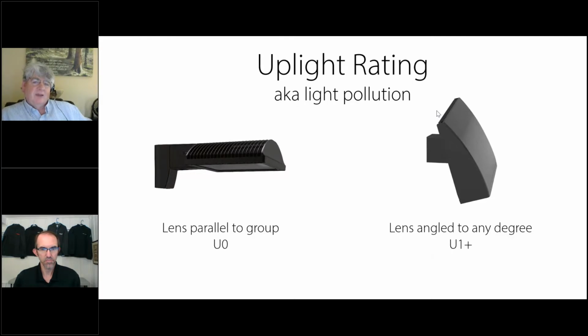The challenge is that there are times, particularly if you're lighting pathway lighting or parking lot lighting, where you actually need vertical illumination to see whether or not somebody's coming towards you. You need to be able to see their face and recognize their demeanor. And so if all you have is downlight and you have no vertical illumination at all, you may have a very difficult time seeing people's faces because they'll be heavily in shadow. So you can't eliminate all uplight, you can't eliminate all vertical illumination, but to the extent possible, certainly we strive to. And so the U0 is a good indicator.